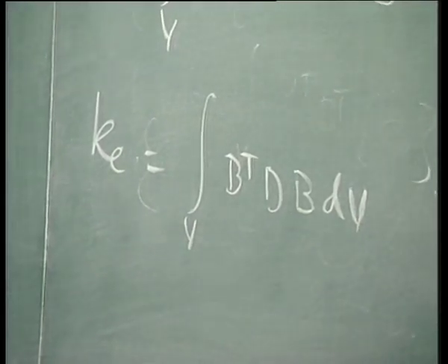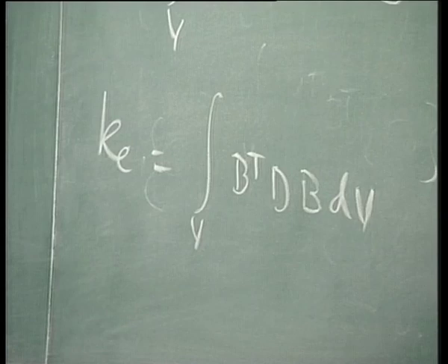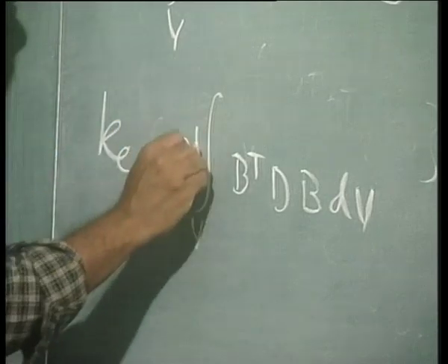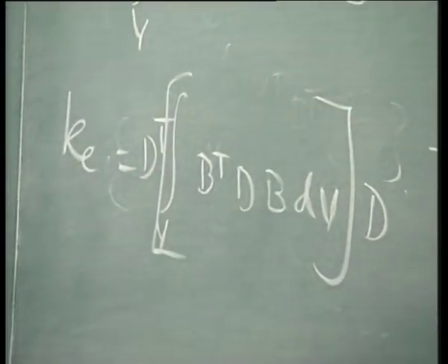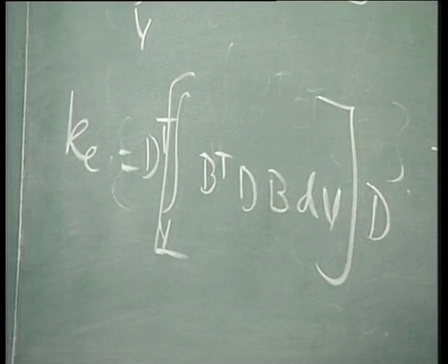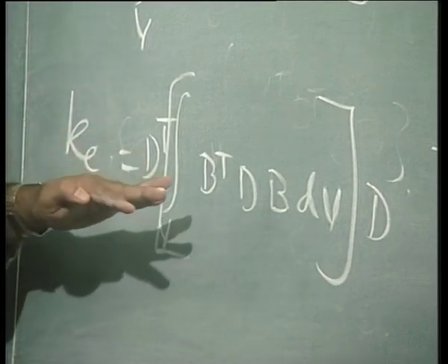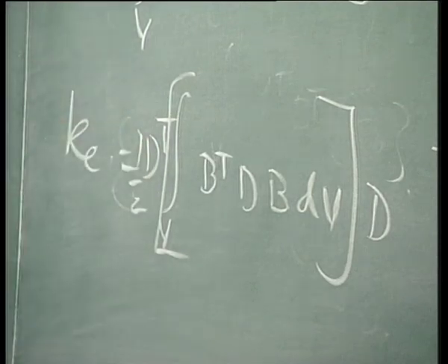Okay. And when I expand it to d, the total phi p of the whole system can be written in terms of capital D. So I can write that d transpose d as a contribution of this element's strain energy, of course with the half there, half as a contribution of strain energy of one element to the total system.